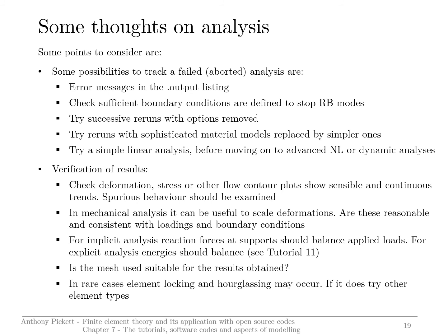This second point I've just mentioned is about scaling the deformations to see if they are sensible concerning the loading and boundary conditions. In an implicit analysis, you should check that the applied or reaction forces which are output to the output files in Calculix balance the applied loads.